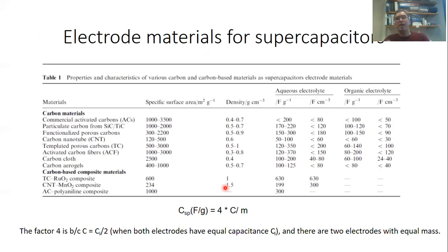But when you have a parallel plate capacitor, you can apply much higher voltages. However, also not infinitely high voltages, because at a certain voltage, your dielectric in your parallel plate capacitor will break down. So this is called the dielectric breakdown voltage of the dielectric.